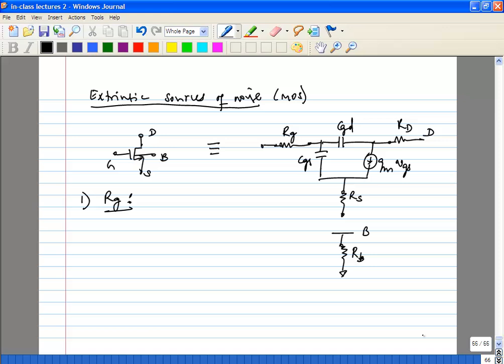So let's say you're contacting down to the substrate, to the transistor drain and transistor source. You'll usually have metal lines, and all you have to do is make sure you have enough contacts to come up to the right metal, and enough metal width for current density and resistance, and you're good to go. Now Rg, it so happens, directly relates to your transistor dimensions. If you have a transistor of a given width and length, drain and source contact through metal directly to the diffusion. The problem with the gate is it contacts from the metal down to poly, which is relatively high resistivity, and the poly itself is the gate.